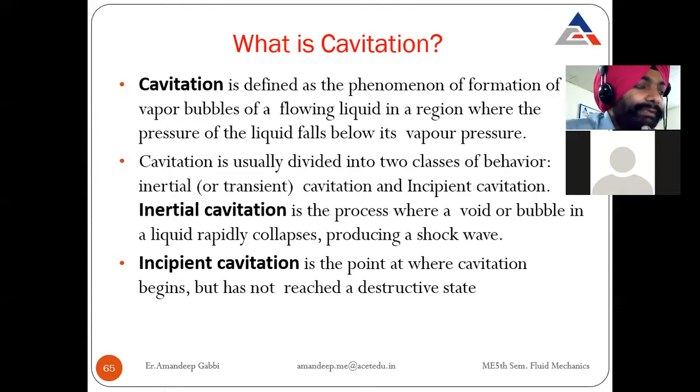So this is an undesirable process in some instrument or device related to hydraulics. When pressure falls below vapor pressure, there is a formation of bubbles. Bubbles then move towards high pressure. When they reach high pressure, they collapse, and the process of formation and collapsing of bubbles is so fast that there is a vibration in that particular machine. Then a shock wave is produced, then it promotes erosion, and cavitation is an undesirable process. Erosion and pitting have happened in some parts of the turbine.